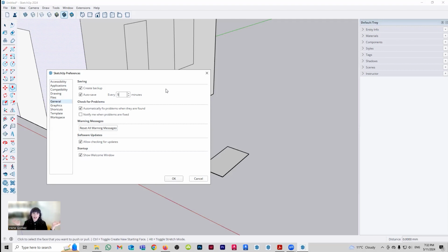And I'm going to give you a good example. I had a student once that came to me very worried, and she's like, oh my God, Irene, I think that my computer has a virus. And I was like, oh no, that's terrible. And she's like, SketchUp virus. And I was like, that's not a thing, but go off. And then she was like, no, yeah, it's a SketchUp virus because I only have it when I'm working on SketchUp. I'm working on my file, and then the computer is freezing all the time. But then when I leave SketchUp, the computer is fine. And I was like, open the preferences. And indeed, what she had was her backup set up to every 5 minutes, and her file was big enough that it was probably taking another 5 minutes to save.